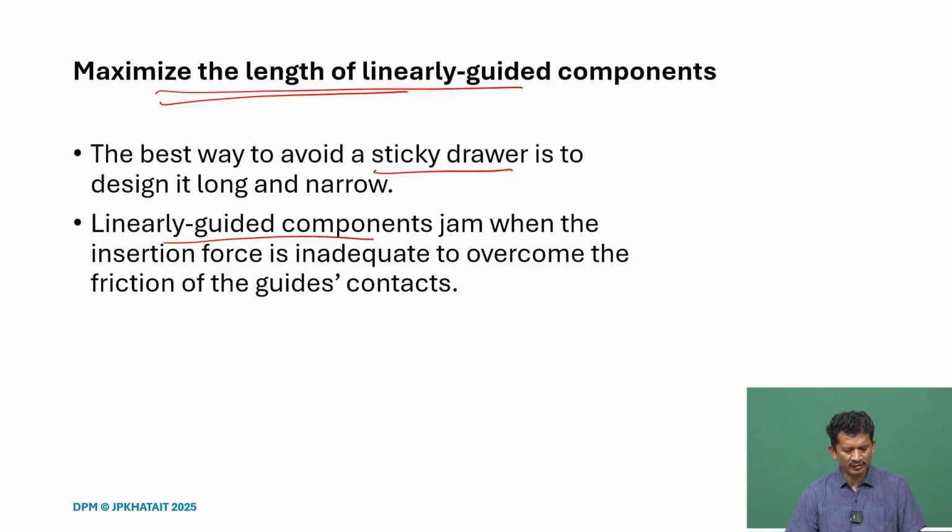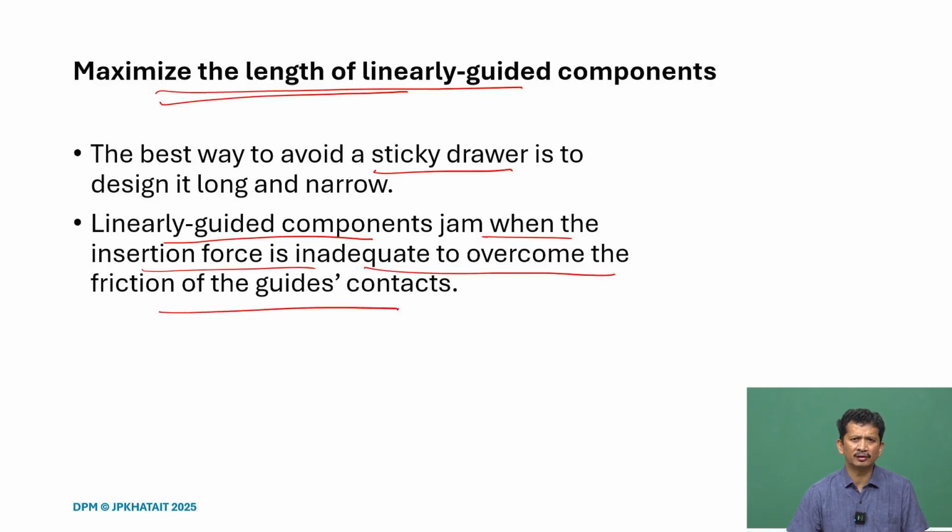What it also says is, linearly guided components jam when insertion force is inadequate to overcome the friction of the guided contacts. If it is getting jammed, the edges will get stuck, and no matter how high the force is, the friction force will also increase, and these kinds of drawers or components will get jammed.